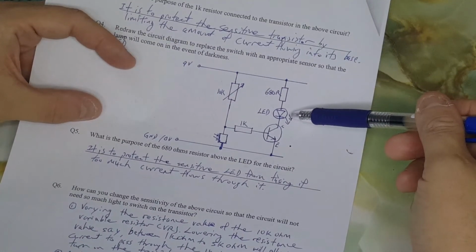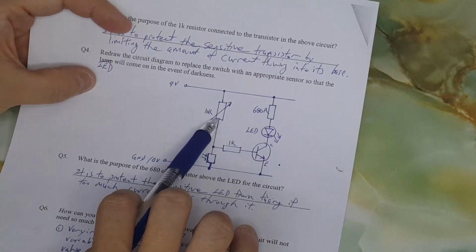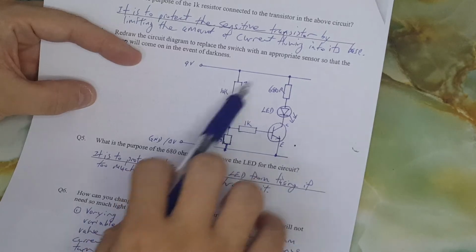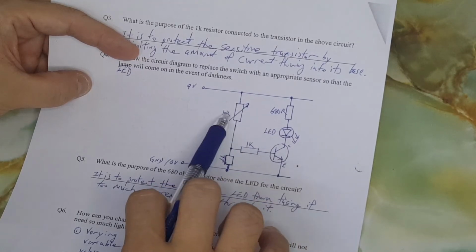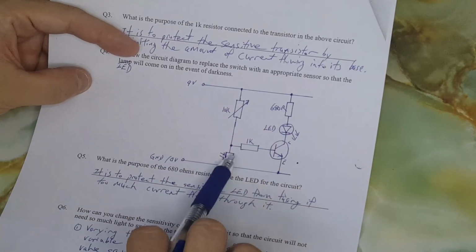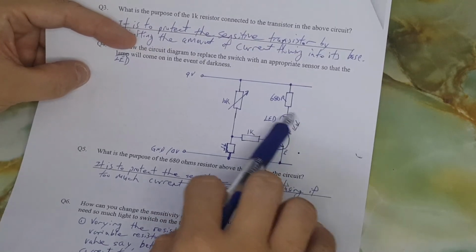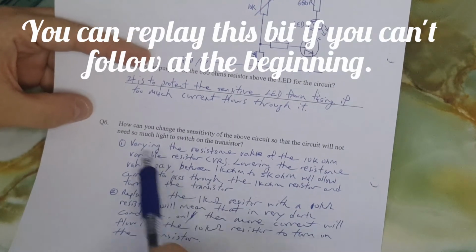on the LED here. So as I mentioned previously, to have the variable resistor here will be the convenient solution because you can actually vary the resistance from 0 to 10 kilo ohms and therefore limiting the amount of current that can pass through the variable resistor in the first place. So if you were to vary the resistance to almost 10 kilo ohms, very high, very little current will be able to pass through. Alright? So what it means in this case is that you will need a very dark condition in order for the little bit of current to pass into the 1 kilo ohm resistor in order to turn on the transistor and hence the LED.